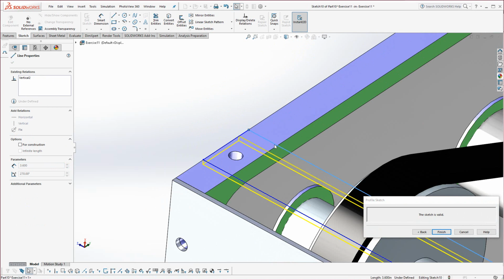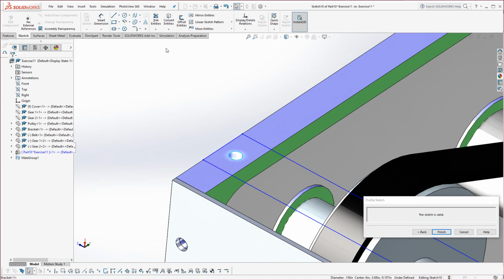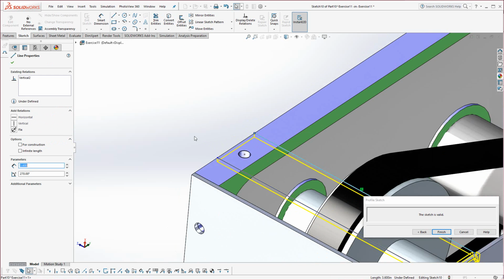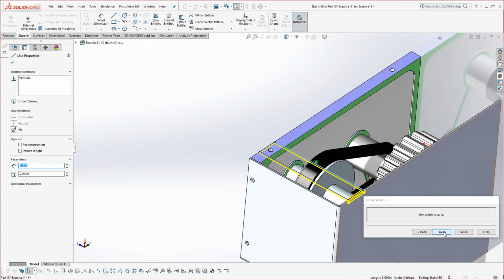And then you could also dimension to it. You could use the dimension tool. You could also steal, like let's say I want to take that edge because I want this flange fastened to it, but yet I want to lighten it. I don't want it to encompass the whole area, and maybe on this side it doesn't need to. Hit the convert entities, and again over here, let's just drag that out a little bit further, and hit finish.